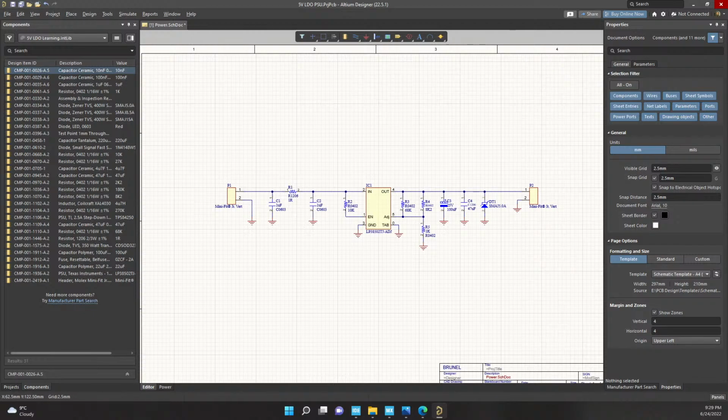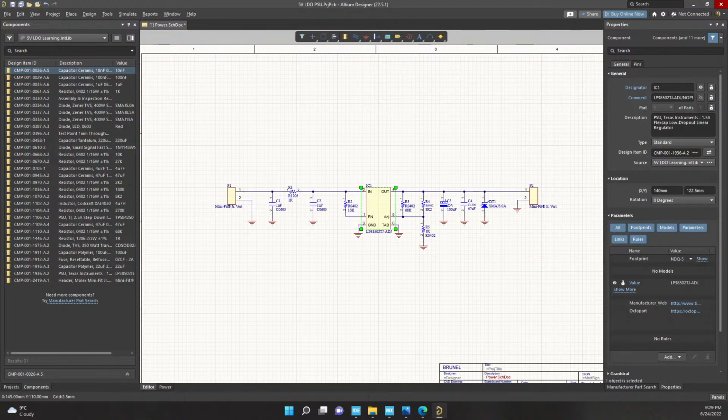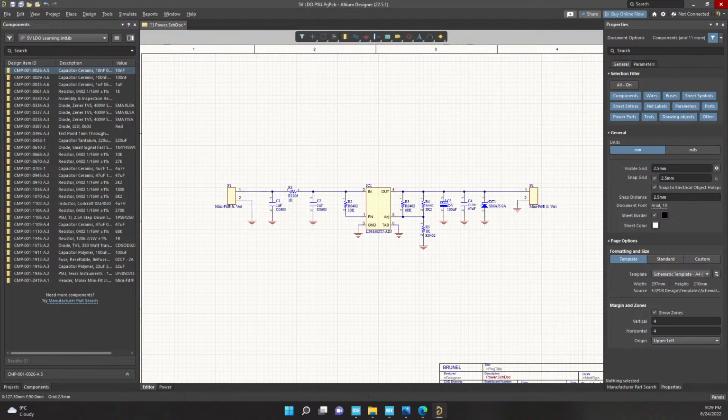For instance, if I look at the schematic, I don't know that this is specifically a 5-volt regulator. I don't know unless I calculate the ratio here, then oh yes, it's a 5-volt regulator. You see, by applying a certain arbitrary input voltage here and reading the data sheet of this thing, right? So without that, I don't even know what's happening here. So we need to make that easy for the person reading the schematic.